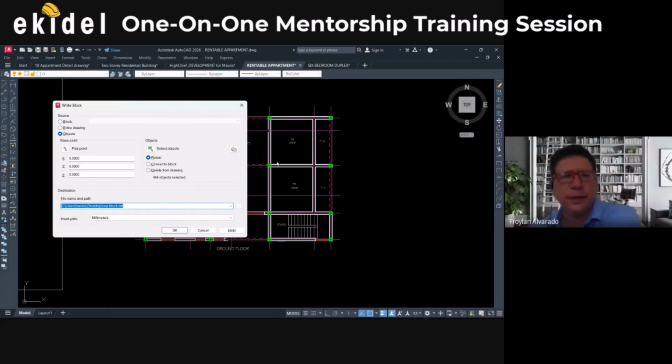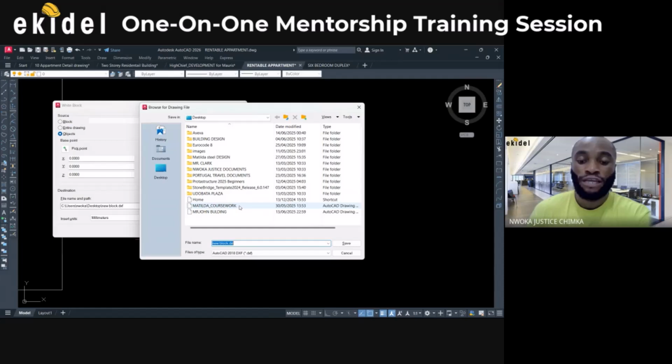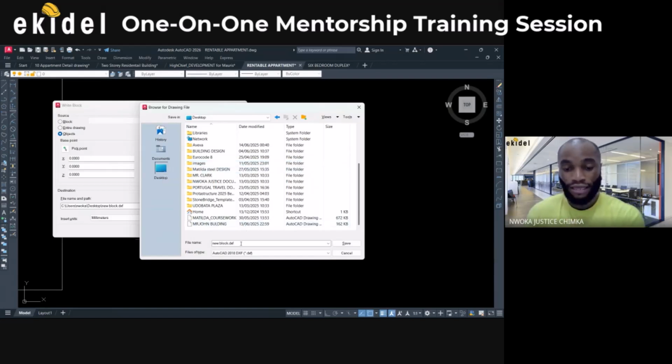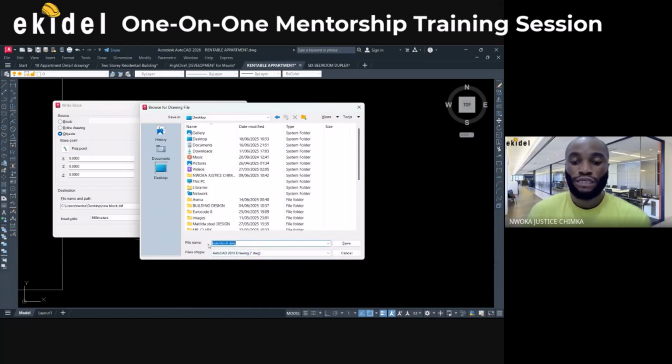environment. So with that, once you have done that, you then click on this icon here that has 3 dots inside it. This square icon, you click on it, and then you have to locate a place in your computer where you want to save the drawing. So let me say I want to save it inside the desktop. I will click on my desktop there, and then I will type the name.